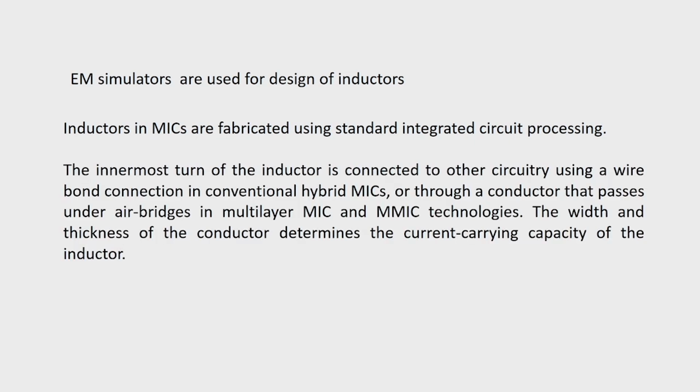The innermost turn of the inductor is connected to other circuitry using a wire bond connection in conventional hybrid MICs, or through a conductor that passes under air bridges in multilayer MIC and MMIC technologies. The width and thickness of the conductor determines the current carrying capacity of the inductor.